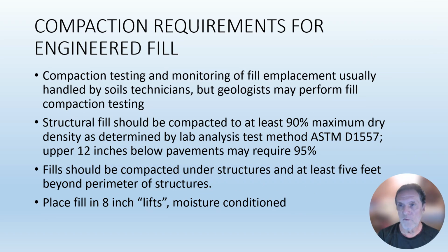So engineered fill, as I've already discussed, you need to compact it to 90% maximum dry density. Below pavements, you may require 95%.